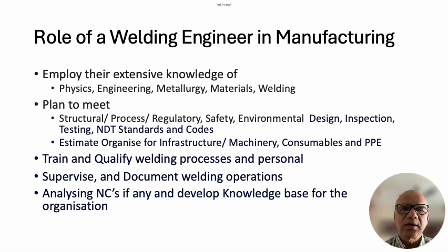and then all this will get translated into design, inspection, testing, non-destructive testing methods and standards and codes. So the welding engineer has to learn, understand each of these aspects, and then accordingly look for what will be the right process, what will be the right manufacturing sequence, and according to that, do we have infrastructure, machinery, and if we have, then what kind of a process and consumables we are going to select.